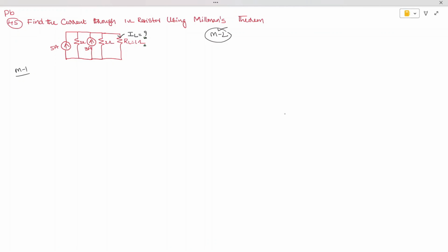See here, this is a little bit confusing. So actually we have to convert this into a voltage source for our convenience. I'm going to apply source transformation to this network. Let us assume this has some node 1 and this has some node 0. Since all are connected in parallel, they are automatically node 1. So between 1 and 0, let's try to identify the elements.